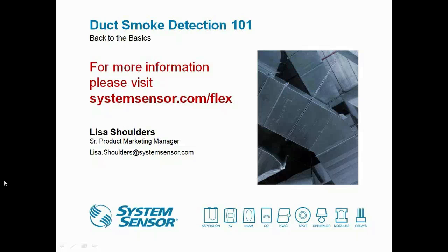Can the option of using two sensors tied back to one power board be done with your intelligent duct detectors? Again, that's a question that we get asked a lot, and unfortunately the answer is no. That feature is only available on our 4-wire conventional models. But if you did want to do it, you can't use the actual intelligent product, but you could tie monitor modules to the conventional product and still achieve the same goal.